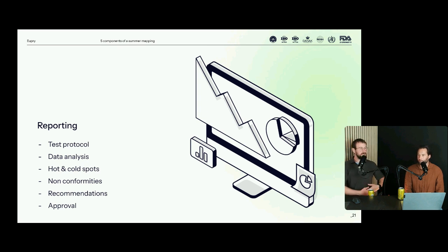In my mind, that doesn't give a full picture. So what we always do, depending on the case, is include a box plot. We basically say, where are 95% of the measurements for each position? It's a very good tool to estimate. We might see one spurious measurement, but consistently, where was the temperature and how stable was that temperature? So a qualified guess based on those graphs, in my mind, is better than just picking out the single highest and single lowest point. That doesn't add value to understanding what the temperatures are.